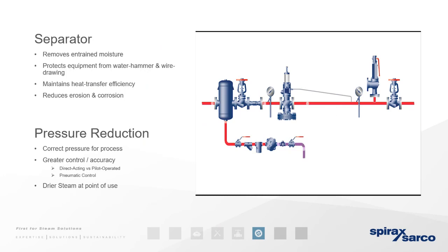One of the first things we do in order to condition the steam is to keep it as dry as possible by removing the entrained moisture that makes it wet. This wetness results in erosion of sensitive areas such as your flow meters and also your valve seats when moving at a fast velocity across them, but also drags the energy of the steam down once we have contaminated steam. By passing wet steam across a separator, the steam condenses on the baffles and the condensate is then removed across a steam trap, leaving the dry steam to pass towards the process where it is now rich with energy and less likely to cause erosion.